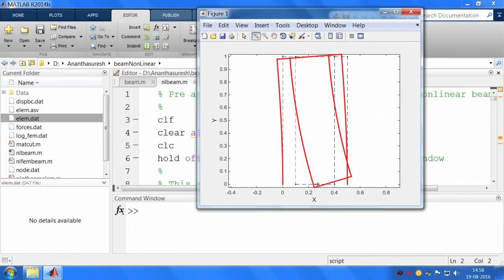I applied a movement at this point about the z axis, out of plane, right. When I do that, it not only rotated, but also has moved. That is called the cross axis influence. That is, you are asking it to move in a particular way, applying force there, but these compliant stages will not do that. They also will try to move in the other directions.